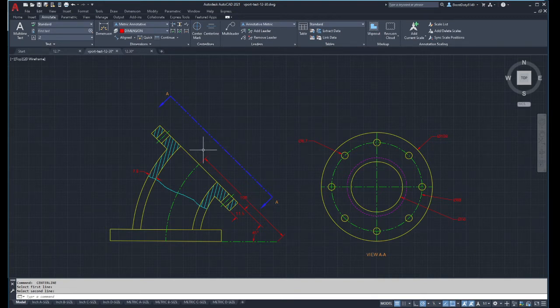Well, I'm not cutting anything, but it's kind of like a camera view. Whenever you create a camera view in some programs, it puts a little camera and it's pointing in the direction that you want to look at. So when you go to that view, then you see what the camera sees. Well, that's what this basically is. This is what we call a viewing plane line instead of a cutting plane line, because I'm not cutting into it, I'm just showing you what I'm looking at.